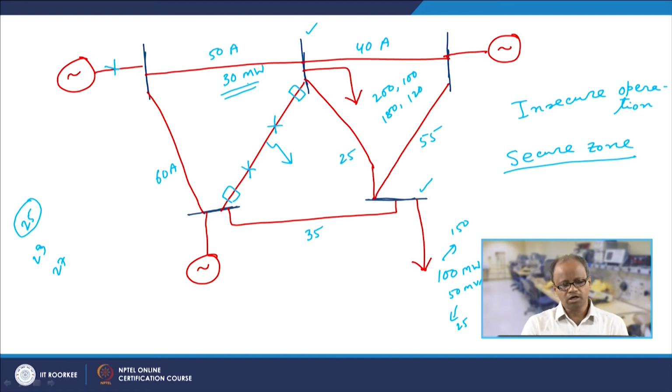Because we are not interested in the accurate new value of the real power flow, reactive power flow, the current flowing through the lines or the voltage magnitudes of the buses. So therefore, it follows that it is not always necessary to perform this many load flows, because AC load flow gives us the most accurate value, but for the purpose of contingency analysis accurate value is not important.